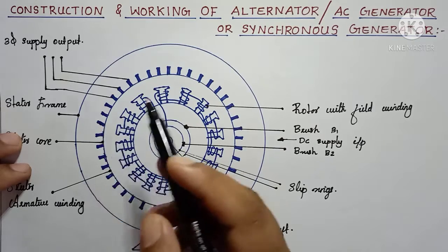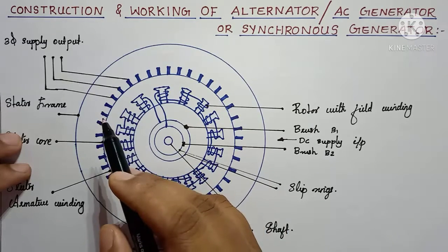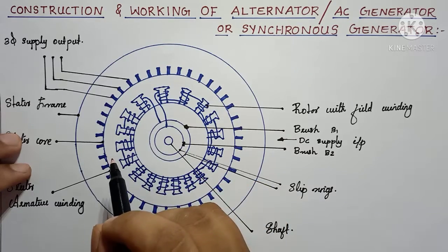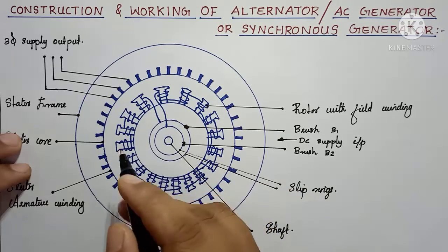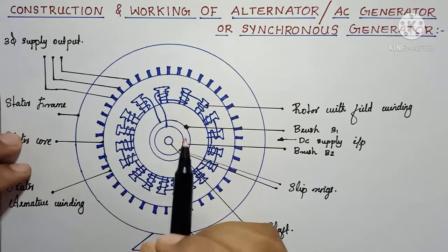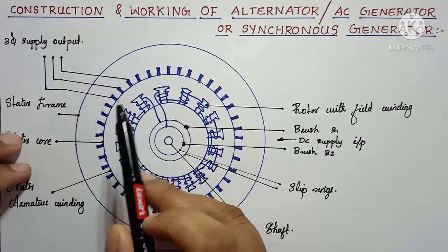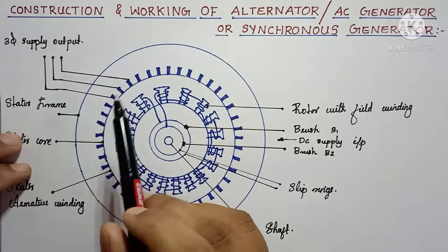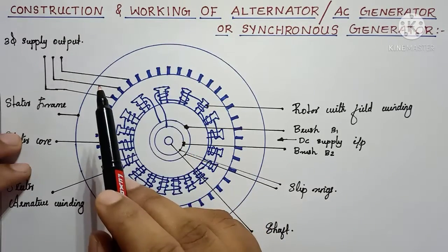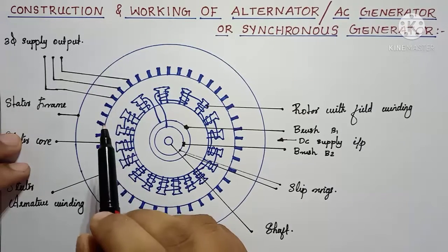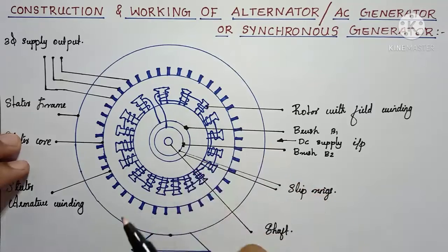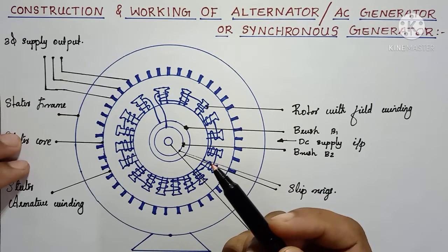Third harmonic effects can also be eliminated, and we know that in star connection no circulating currents are there, so heating losses can also be reduced. So we will get a safe operation. Okay, that is the working principle of the alternator.